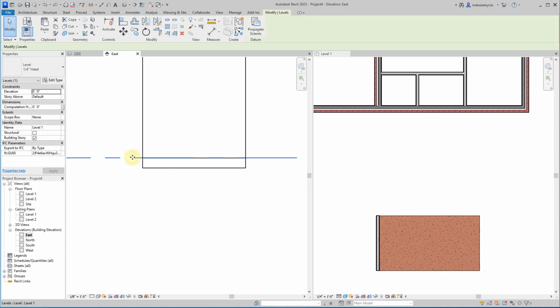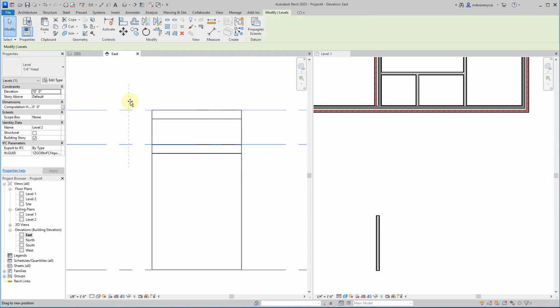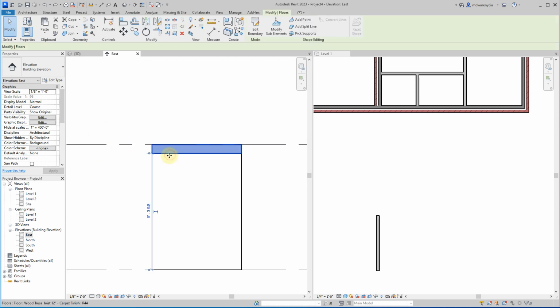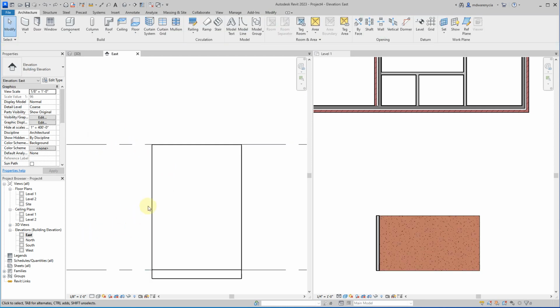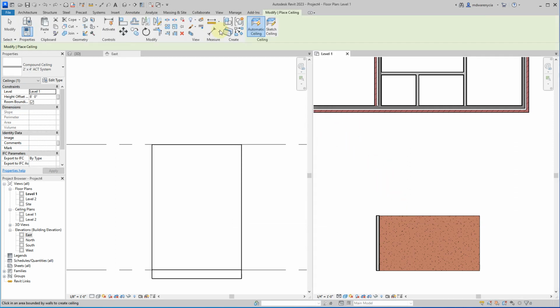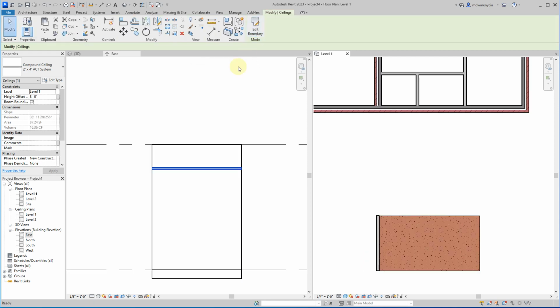So if I move this floor height, actually let's move this up to level 2. If I adjust level 2 again, that floor is going to stick with level 2 wherever it goes. Right? So it's important that you assign things to the floor that they're associated with. In the same way, if I go in and add a ceiling in here, and we're going to go to floor plan level 1, if I sketch it, and we'll do the same outline here, green check mark to apply it.